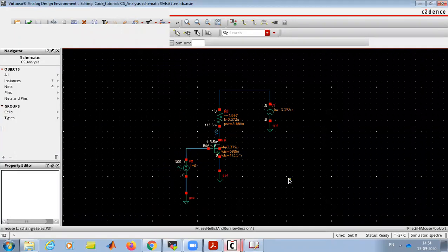So for this noise design of an amplifier, for a particular application, we should be very clear for which application we are designing our circuit. Based on that, we see what we need to optimize. Sometimes noise is a higher priority, sometimes gain, sometimes bandwidth, sometimes swing is the higher priority. If you read Razavi's book, there is an octagon, which we call the analog octagon. There is always a trade-off, but based on the priority, we design.